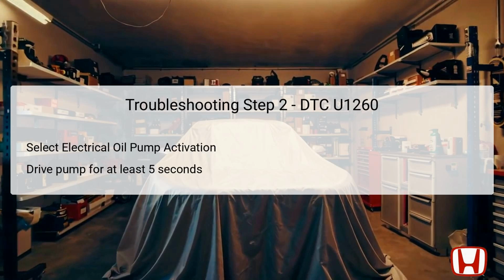In the second step of troubleshooting DTC U1260, the technician will utilize the HDS to select the electrical oil pump activation function from the menu. This function allows the operator to command the auxiliary transmission fluid pump to operate for a specific duration of time, at least 5 seconds in this case. By performing this action, the system's response can be evaluated, and it is crucial to observe if any pending or confirmed DTCs arise following this activation test. If the DTC U1260 reappears, it indicates that the failure has indeed been duplicated under controlled conditions. This duplication is vital for confirming the validity of the original fault, providing a strong basis for further troubleshooting steps.